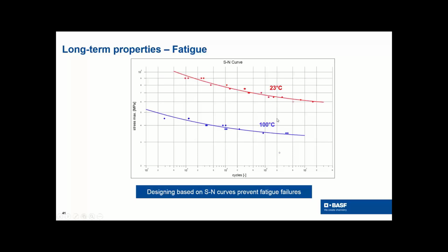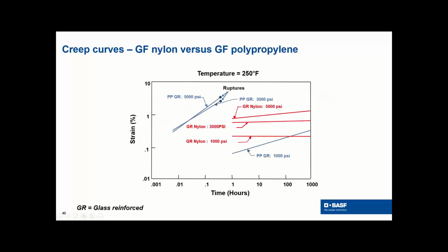So if you would have to design a new fan or make this fan blade a little bit fatter, the blade thickness-wise, now what you should target here is probably around 30 megapascals in this area here. So huge difference. So understanding, again, as we talked about temperature, your temperature extremes is key in any property, including fatigue.